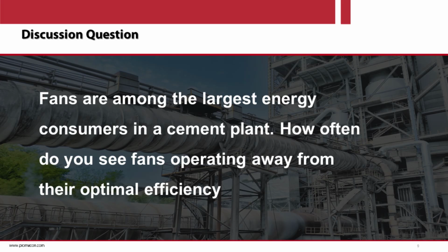And that can be done online or over time periods. But when we measure it in the plant, we're usually finding that they're off by about 10% or more from what the original fan curves say. So knowing the fan flow, you can calculate the efficiency very quickly. And from the efficiency, you can start to determine what's causing the inefficiency and improve that situation.